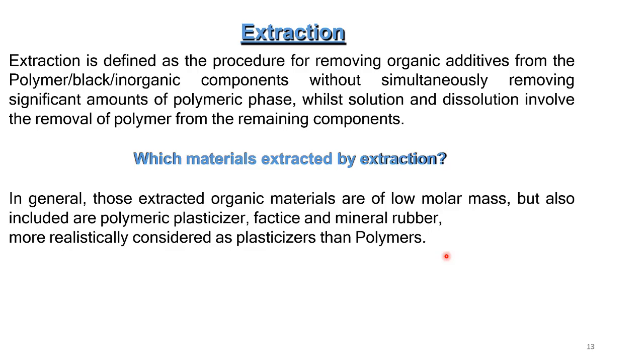This is a procedure for removing the organic additives from the polymer, carbon black, or inorganic compound without simultaneously removing a significant amount of the polymeric phase, while solution and dissolution involve the removal of the polymer from the remaining composition. So extraction is different from dissolution, because dissolution removes the polymer also, but extraction only removes the organic additives from the material.